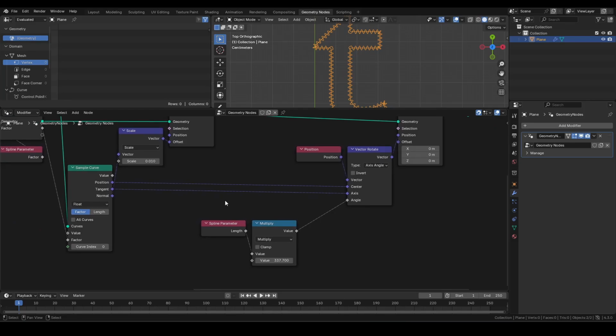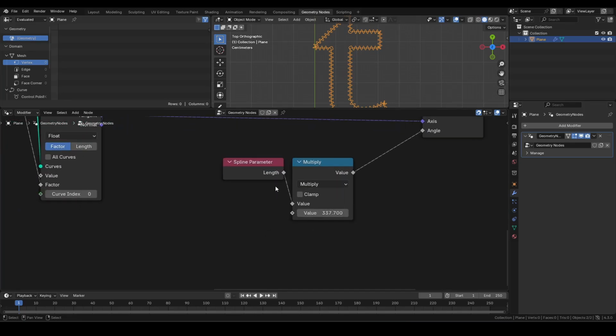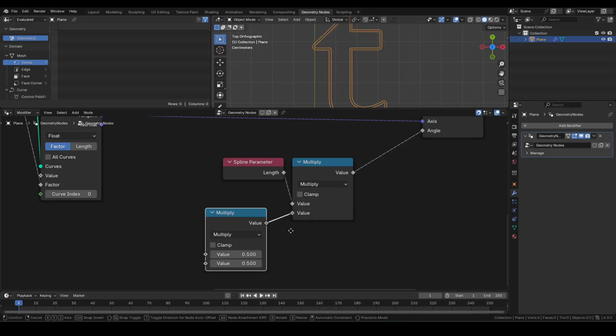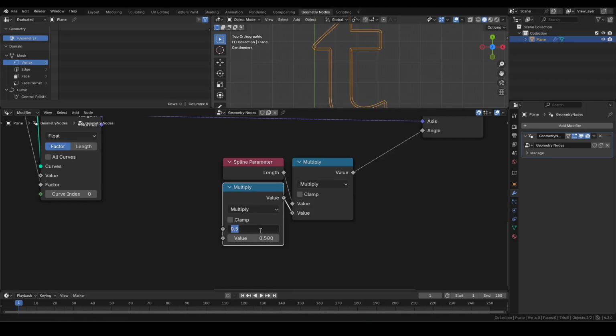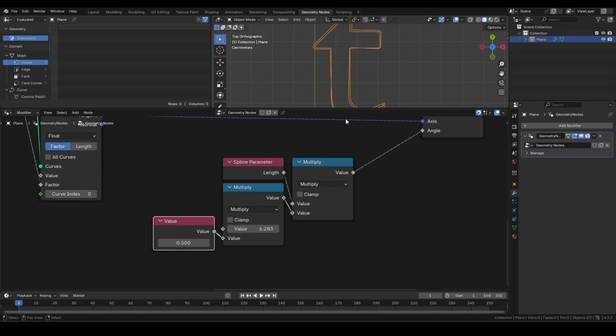I don't like how this multiply gain is an arbitrary number. So connect another math multiply. Enter tau to the top and connect the value node from the bottom. This should now represent the wrapping amount per unit length. Entering 10 means 10 turns per 1 meter. 50 per meter looks something like this.